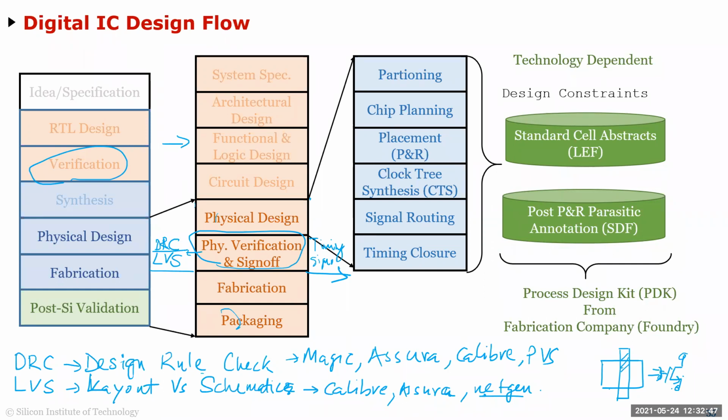So process variation is one, and then it could be data dependent also. What I mean by data dependent is when we do combination logic, you'll realize that a NAND gate, for example, depending if one of its input is high or low, the other input going from low to high, the propagation delay will be different because the RC delay is different.